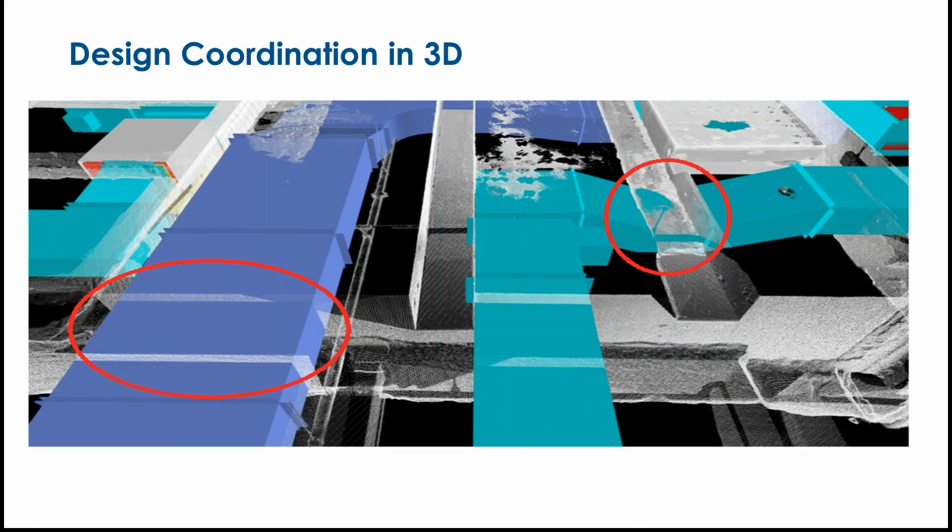Going on to the question for the gentleman that uses Plant 3D, I don't know if you're familiar with Qubit or if you're working on any projects currently with 3D scanning. I'd love to hear if you already have experience with processing data for use in Plant 3D. Qubit has software that automatically extracts the piping and automates the process of placing valves and bends and all of that, and then it's all spec driven based on your settings in Plant 3D. So you would export out whatever spec you were using for Plant 3D and just apply that as you're extracting the information from the point cloud.